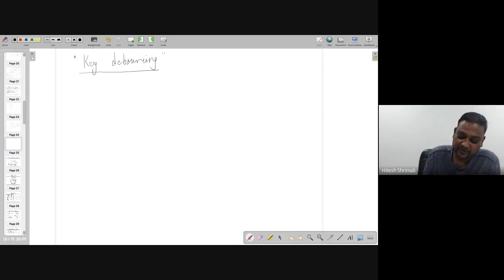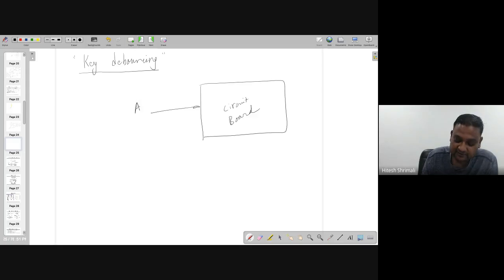Let's say I have a push button and a digital circuit board giving input A or input B. But sometimes when we were connecting through a push button, this is not considered one of the best solutions, because the input goes like this when it's 1, or sometimes there is some bouncing and then it goes up, or sometimes like this and goes like this, right?